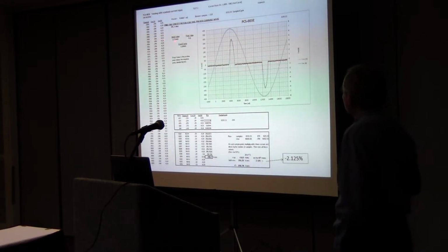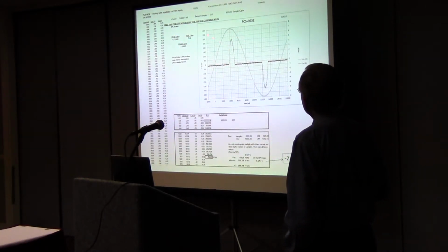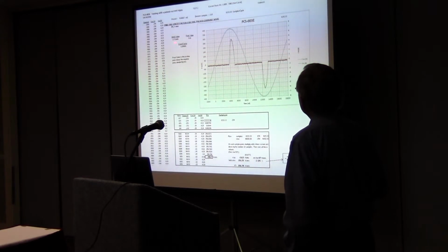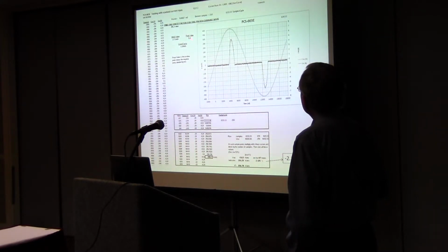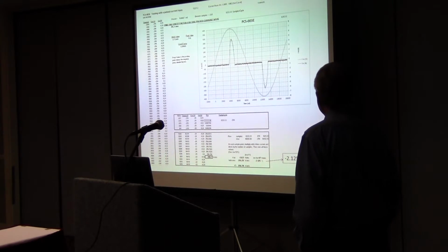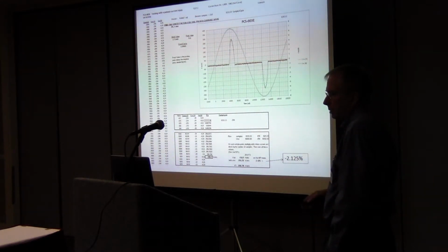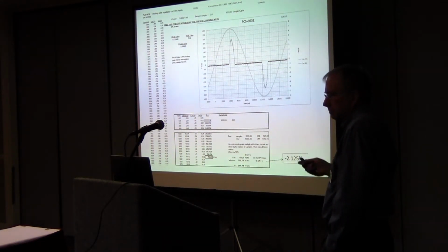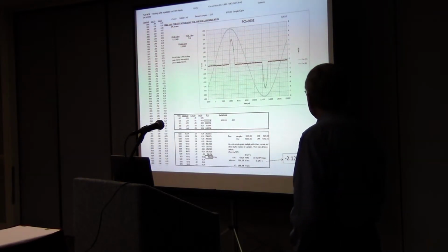Now, kind of small up here, but this current waveform had an RMS value of 1.7 amps, yet it had a peak value of 5.8 amps. So this was low enough that our transducer could handle the peak of that without saturating.